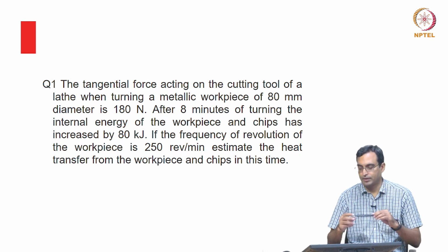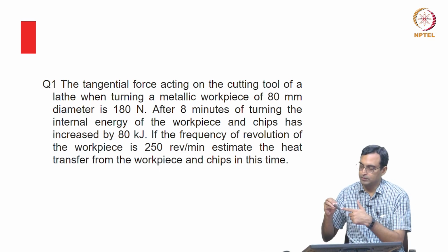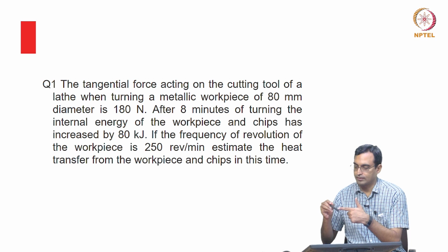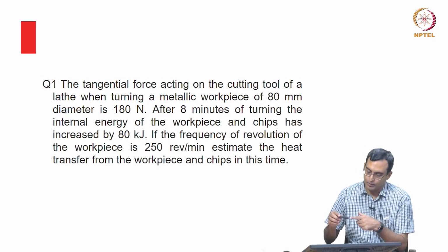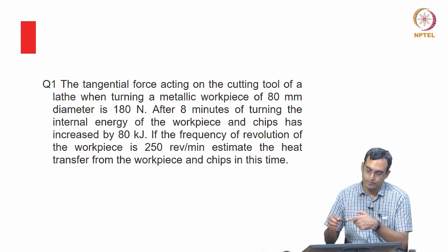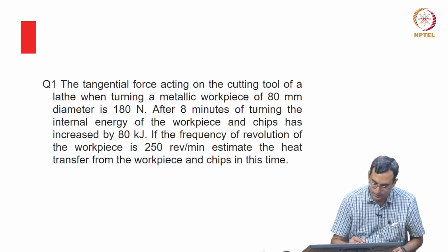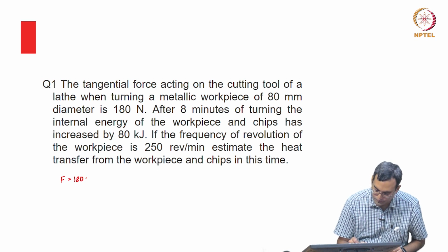So you have, for example, a rod which you want to turn. The rod is fitted on the chuck and it's rotating, and you have a cutting tool which is going to be somewhere like this, and this is rotating and this is cutting and progressing. So what we see is that the tangential force because of this cutting tool is 180 newtons. So the force is 180 newtons.